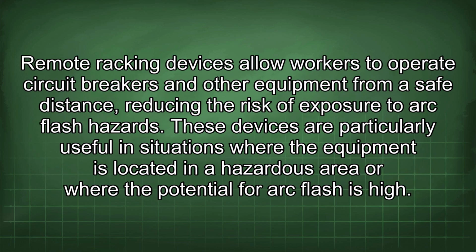Remote racking devices allow workers to operate circuit breakers and other equipment from a safe distance, reducing the risk of exposure to arc flash hazards. These devices are particularly useful in situations where the equipment is located in a hazardous area or where the potential for arc flash is high.